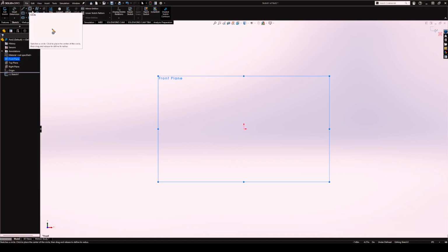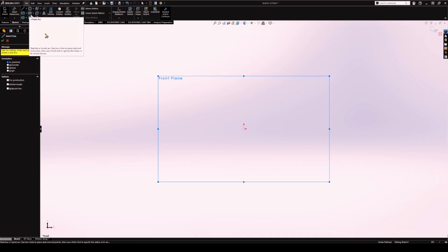Now this center point right here, this is your origin, and what we'll do is use our drawing tools to create that box. Now you can use your lines, or you can just use a simple rectangle. For simplicity, actually, you know what, let's use the line tool just so we can talk about this. So we'll click the line tool, we'll come over to the origin, and notice you have this line here. That's a reference to your axes, and you have a little reference down here to see which way you're drawing.